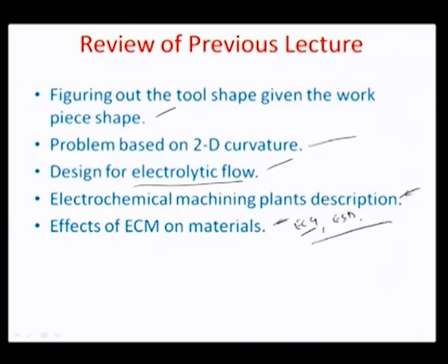After the review of these fundamental electrochemical machining processes, we will start over again and try to apply some of this technology to the fabrication of microsystems, for example microneedles, very small, superfine, high aspect ratio structures used in the area of MEMS or microsystems. These can be fabricated using such machining protocols by localized deposition of material at a certain place, which we will talk about a little later once the slides begin on the applications of electrochemical machining on microsystems.